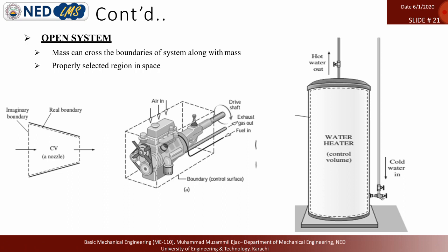Now move to the open system. An open system is a system in which both energy and mass come in and out. In applications like a nozzle, or the gas turbine engine in the aerospace industry, the hot gases go into this nozzle, and that pressure converts into velocity. The resultant compressed air is combusted and gains temperature. So the exhaust gases have both high temperature and high pressure, and that energy converts into velocity.